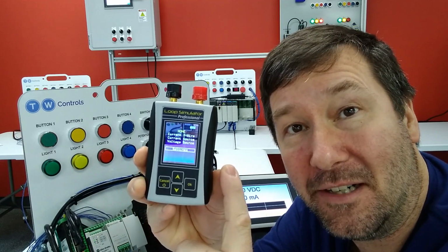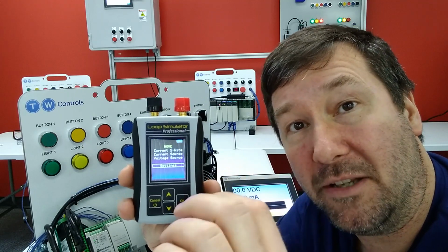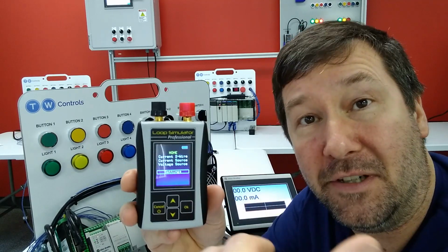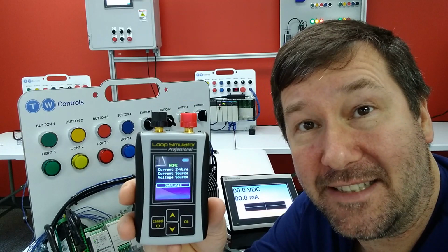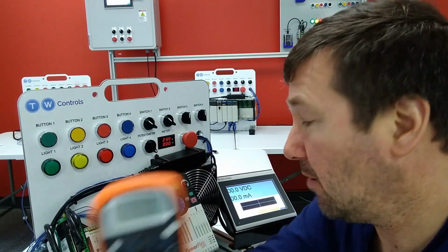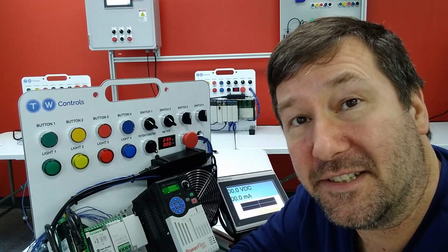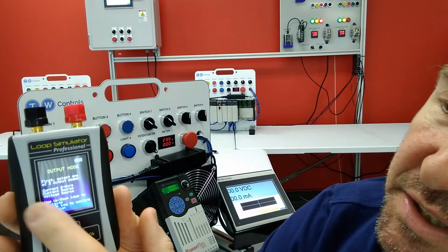Today we're going to take a deep dive into the features of the PLC Tools SIM-ALP2 analog simulator. This device is very popular with technicians that need to simulate 4 to 20 milliamp current signals and 0 to 10 volt signals in fields such as industrial automation, HVAC, and the oil and gas industry. We're going to simulate signals to both a basic multimeter and to a PLC, since those are the two most popular connections. The first time you power up your SIM-ALP2, it is going to come up with this quick start guide.